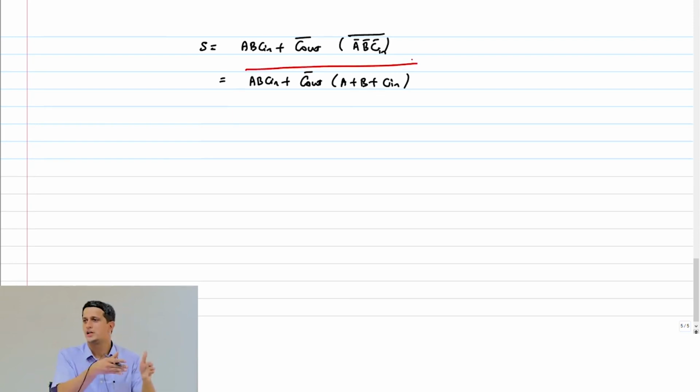Then you write the boolean inside, right? Then you can say that when the Cout becomes Cout bar, I can invert if my inputs invert. But still you have to show that the mirroring holds, is all I'm saying. You either have to enumerate truth table or you have to show it here. Clear?